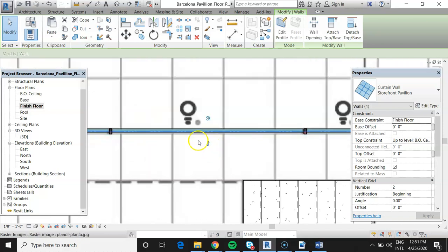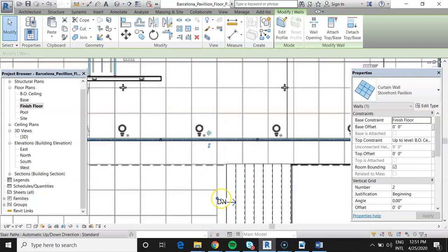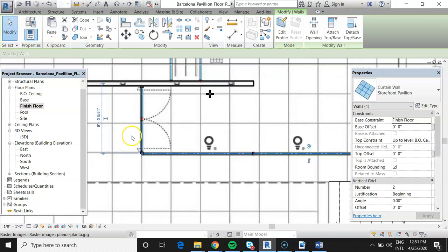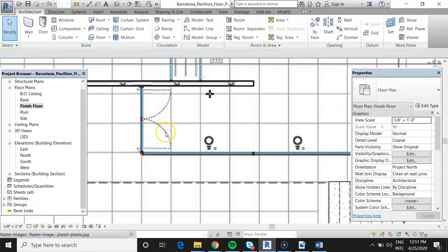This is telling us that this is the exterior. For our generic walls, it didn't matter. For our storefronts, it does. Okay, we're outside the pavilion here near the stairs, and we want this to be the outside facing piece. And we'll check here, and we got the same. Okay, so the outsides are facing out the way they should be. Good.